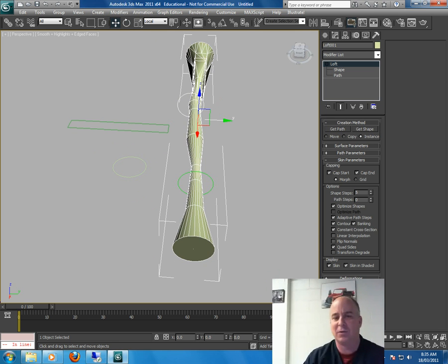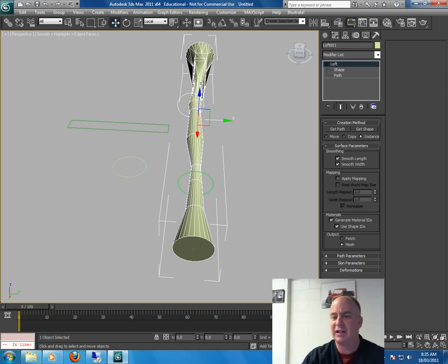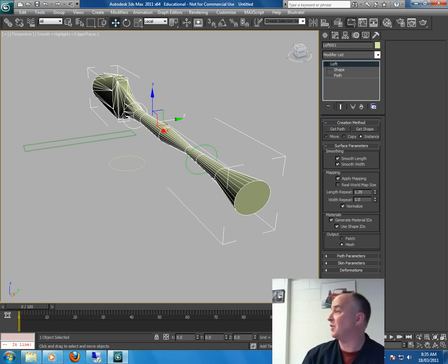And you can flip the normals. You can get into linear interpolation. There's a lot of things. But one of the most important things of lofting is the texturing. Because if you have a tile texture that you want to follow your loft line, they automatically generate the mapping and you can length repeat your textures. It's really insane with lofting, especially for roads and other things that you want to follow a dashed line along the side of your object. It does it automatically. So anyways, I just thought I'd show you this weapon loft method.